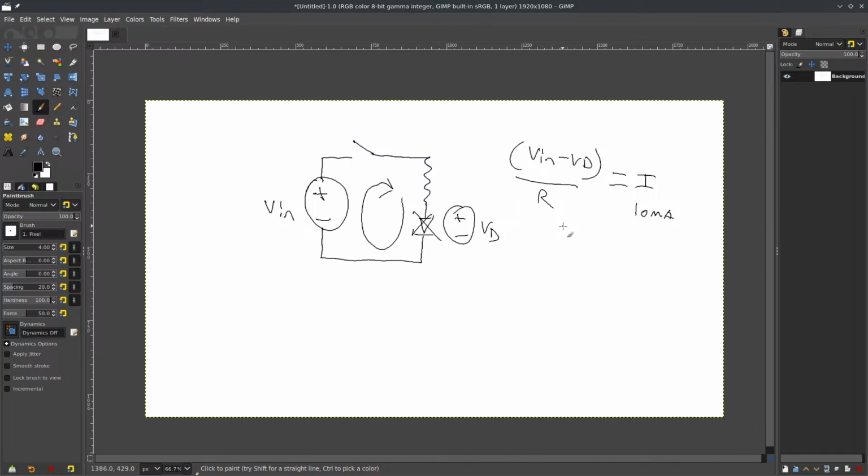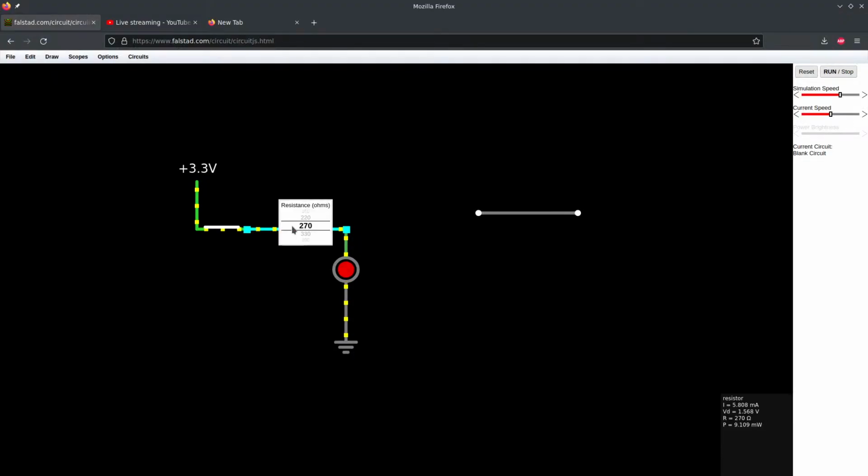I will say though, don't do 10 milliamps from the microcontroller unless you check that it's okay. A lot of them, like I'm pretty sure there are multiple pins on the STM32s I've used that are 0.5 milliamp drive only. I'm going to get to another circuit in a second as to why. So aiming high on the resistance to make sure the current doesn't become an issue is not such a bad thing to do here. Let's do 470 ohms. That'll work.